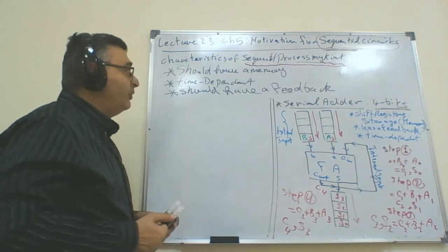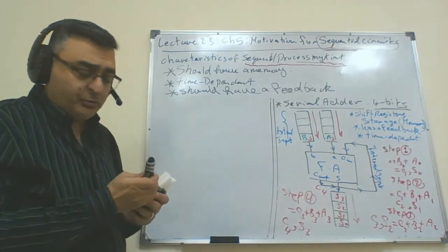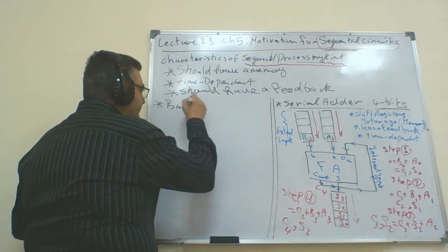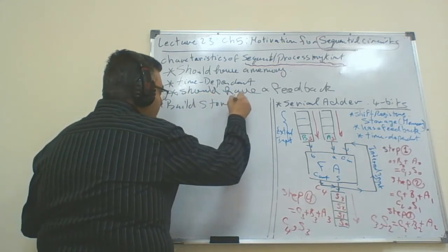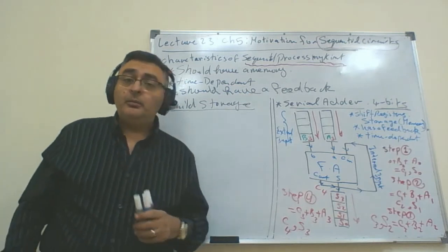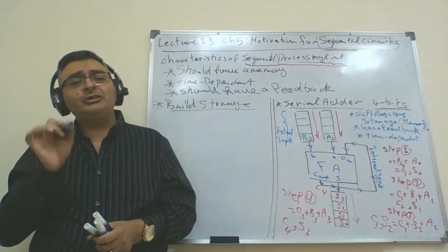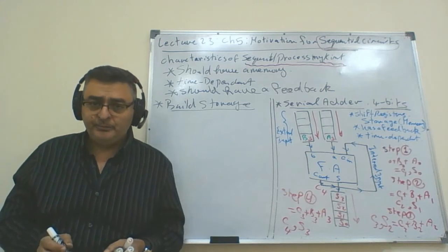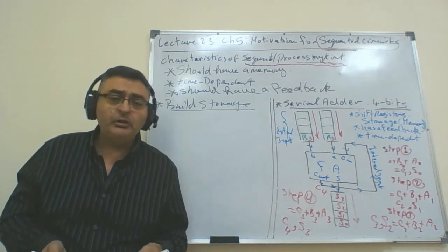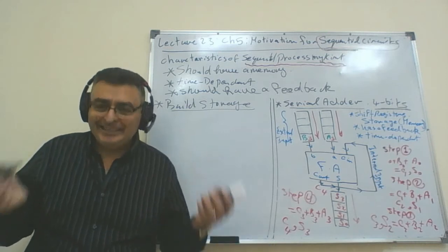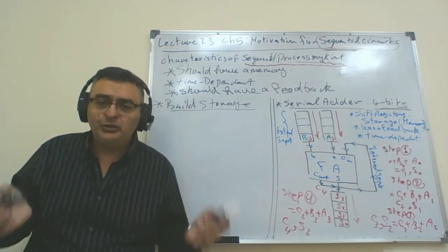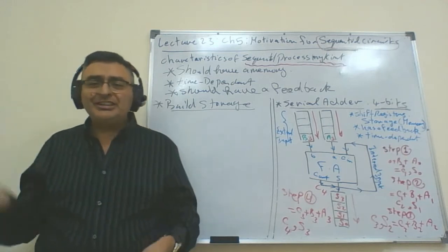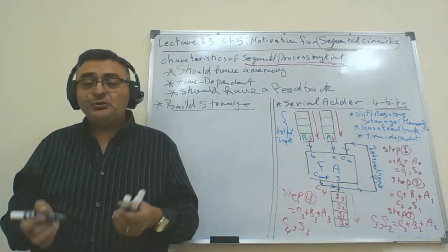So our first mission in synchronous or sequential circuits in general is to build a memory or a storage. How can I build a storage? Building a storage from digital logic design circuits using the logic gates that we have already learned. We will not bring new components. We will not manufacture something new. Still, the logic gates that we have used through chapter 2 and 3, ANDs, ORs, inverters, NANDs, NORs, will be used to build the memory.